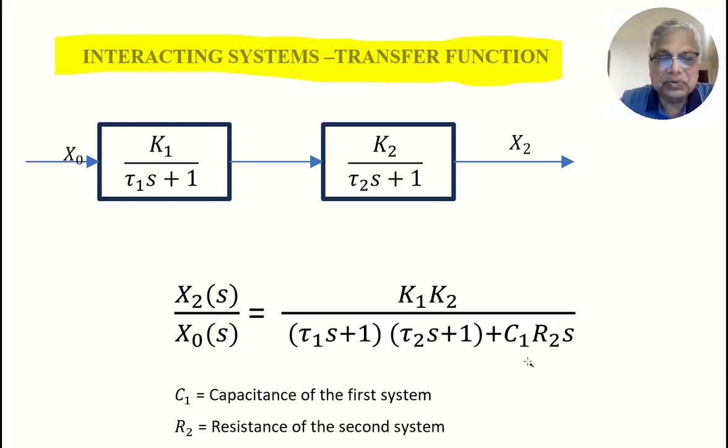The presence of this extra term C1R2S in the denominator is going to change the dynamics of interacting systems as compared to the response of the non-interacting systems. So let us see what will be the response of this for a step input and see how it behaves.